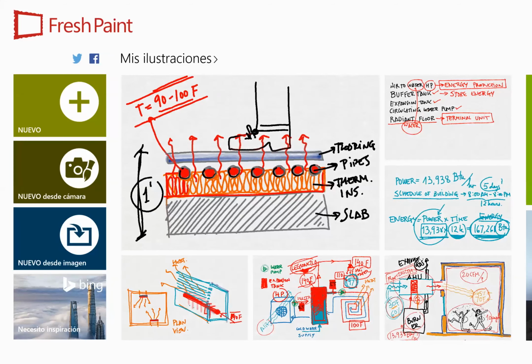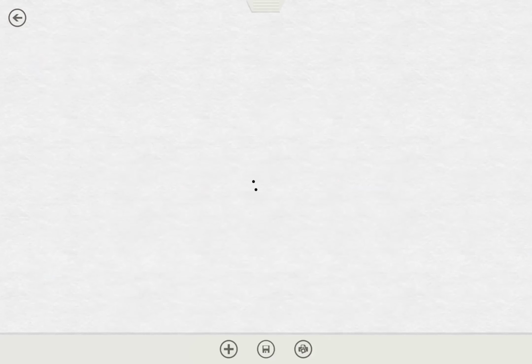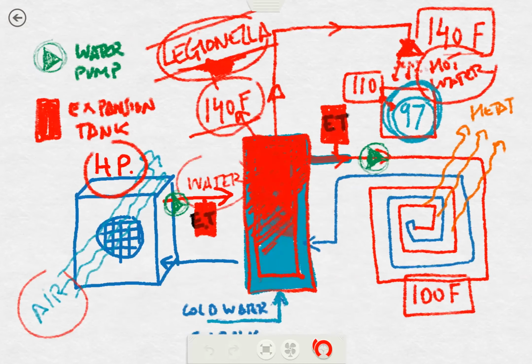But anyway, if we are looking at this system, we need a heat pump, we need an expansion tank here, we need the radiant floor, and then we can provide the house with hot water for showers or whatever. So that's it. This is the easiest way to heat up a house. Instead of a heat pump, we can have a burner. We can have a condensing gas boiler. We can have a pellet boiler or whatever. Anything that heats up water, we can have it here.